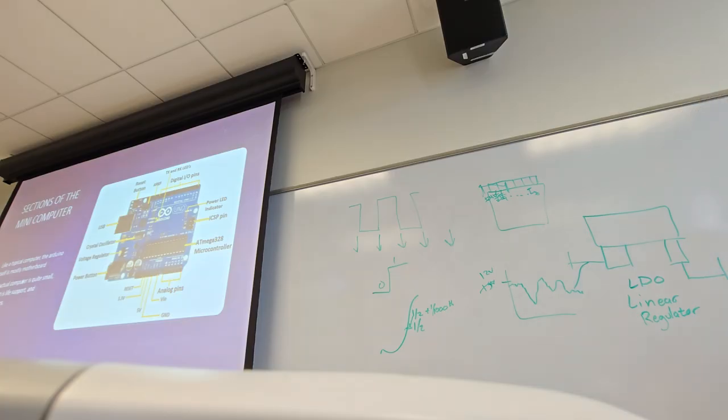These are also simple, extremely cheap devices. They cost like 5 cents each, 10 cents each, these ICs. But the downside is they generate heat. Because of the difference in voltage, if we go from 12 volts down to 5 volts, that 7 volt drop is dissipated as heat. And the bigger the voltage drop, the bigger the difference between our input voltage and our output voltage, the more heat we'll generate. It's just waste. It's inefficient, but it works.